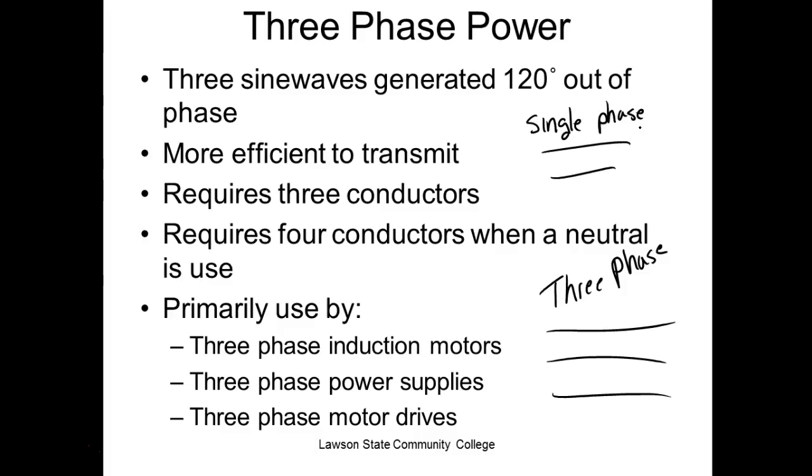But three-phase is a lot more expensive because I have to use at least what? Three conductors. Can't you imagine three conductors going everywhere we have power? It would be wonderful, but it would be very expensive. So low wattage loads like our house has no need for three-phase. So our house gets single-phase power. Big industries, high power demands, they give them three-phase. Now, it doesn't change your bill, because you don't pay for three-phase, you pay for watts.